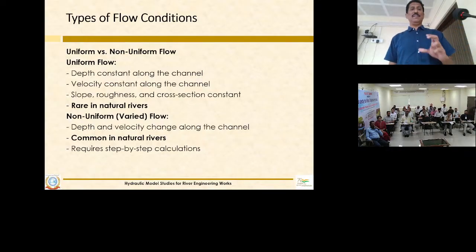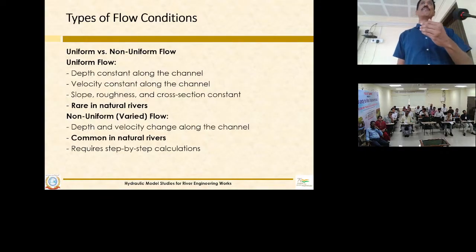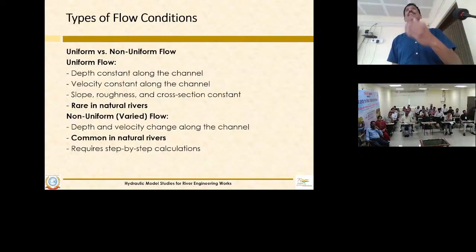If you consider all the equations we learn, they are basically derived for uniform flow. For Bernoulli's equation and others, there are assumptions, when we see the hydraulics books or open channel books, that the flow is prismatic and uniform. We generally ignore this condition and don't read it, but these equations are developed based on uniform flow and prismatic channel flow.